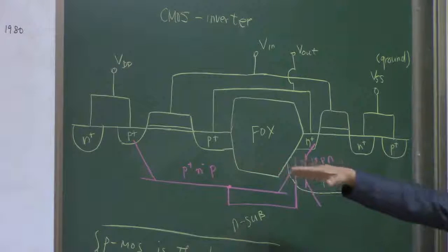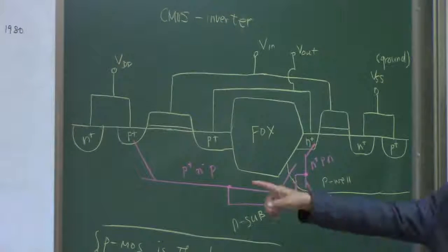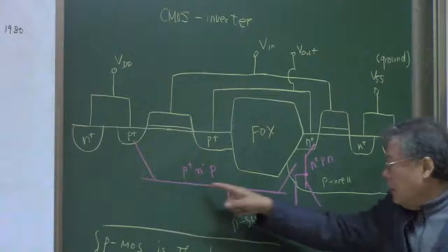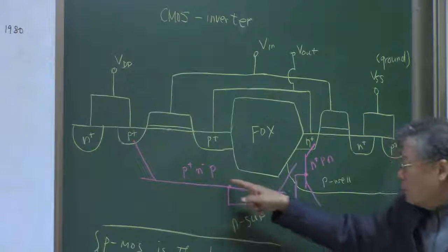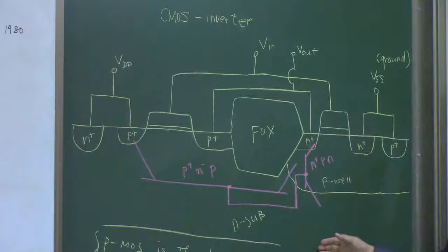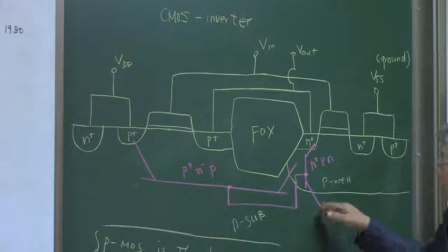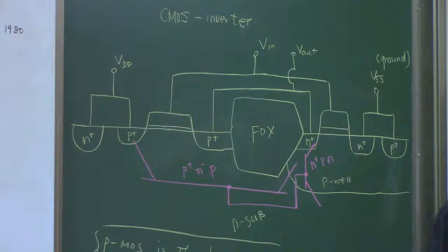It just has been constructed on the same silicon wafer in the two-dimensional silicon surface, so that if there is a way for the electrons and the holes to get a path, then those free carriers can see the bipolar structures, one lateral bipolar structure and one vertical bipolar structure, and then if these two bipolar structures can have some current on the base, then the bipolar transistor is going to be triggered on.